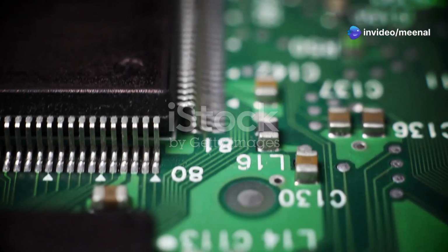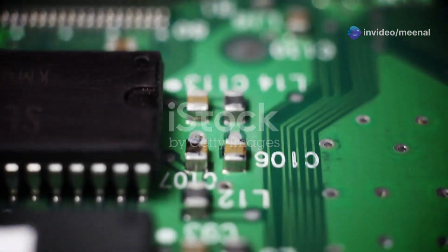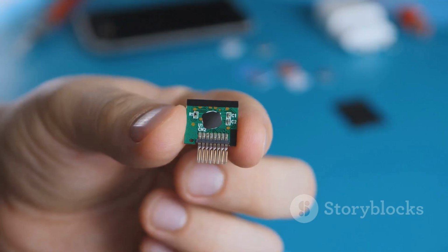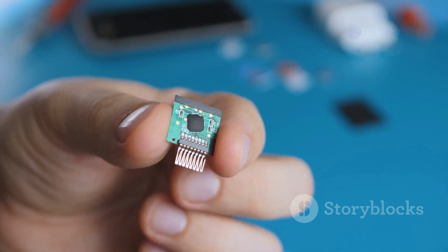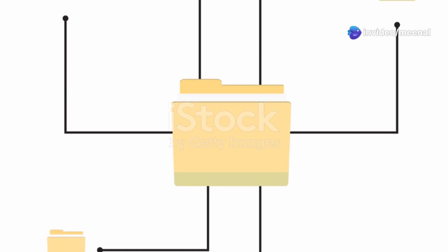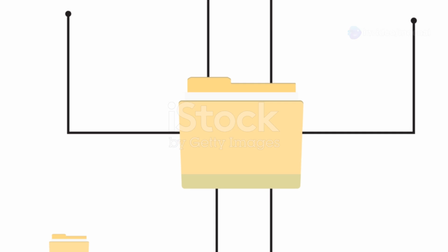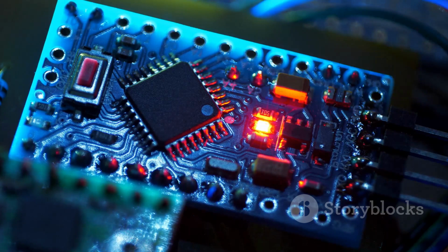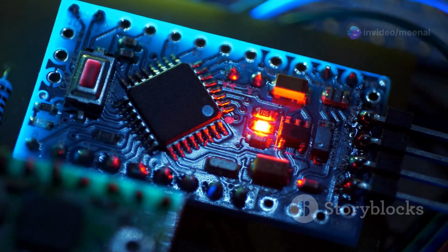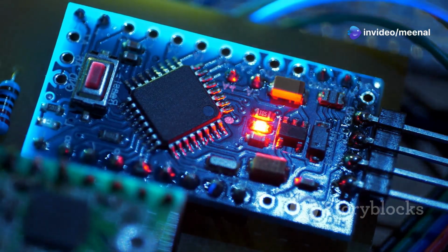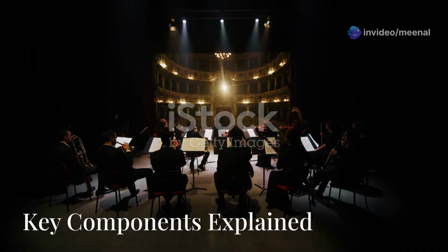The master device is usually a microcontroller, while the slave can be a sensor, a memory chip, or even another microcontroller. The master initiates the communication and controls the flow of data. It sends commands to the slave and reads back the responses. The relationship between the master and slave is crucial in SPI communication. It ensures that data is transmitted correctly and efficiently, much like a well-conducted orchestra produces beautiful music through the coordinated efforts of its conductor and musicians.